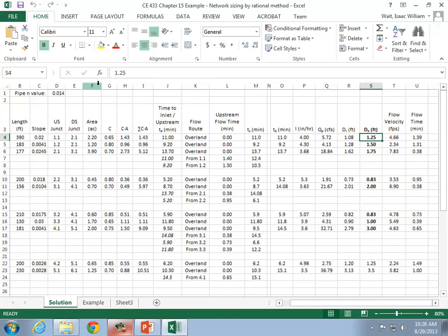And so you're not going to get very much runoff quite yet, because even though it's raining really hard, only a small fraction of the total area is contributing. Another 2 minutes, so 4 minutes later, all of a sudden you've got this much of the area that's actually contributing flow to that inlet.